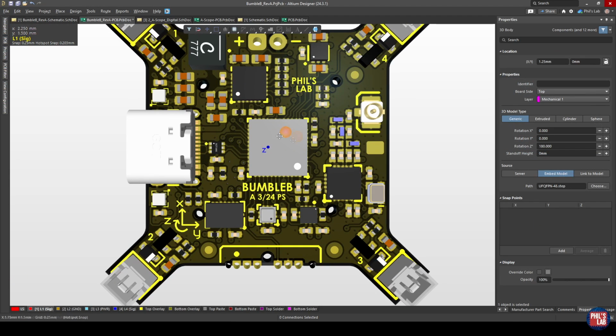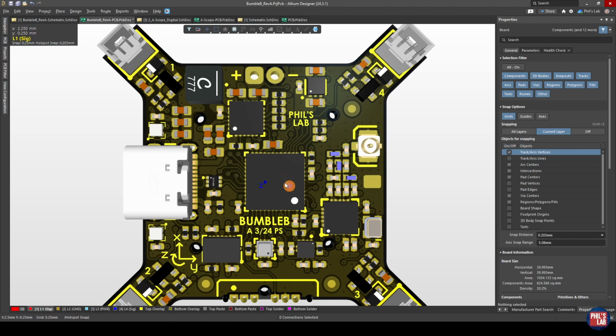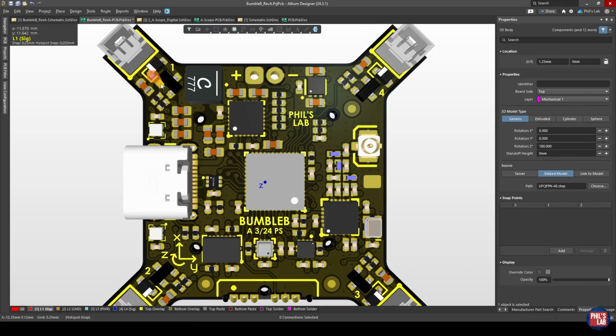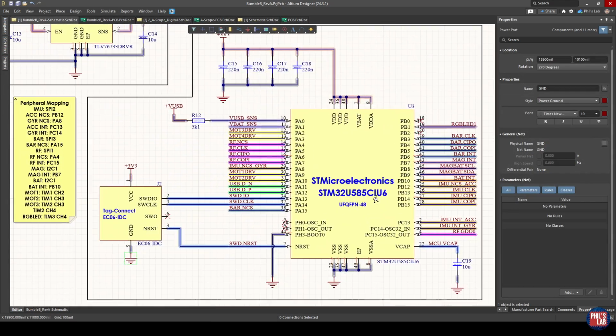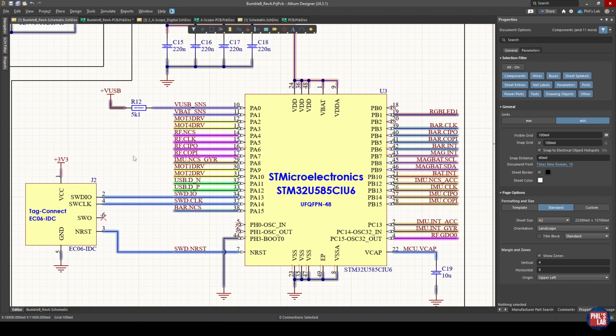Again, we have a microcontroller in the center connected up with various peripherals that most of the time, in 3 cases, use SPI to interface back to the controller. In terms of the schematic, looking at the microcontroller section, you can see I'm actually using separate SPI buses and interfaces between the various peripherals. This is again because I want to be able to use DMA and do parallel data transfers, for example, from the barometer, the accelerometer gyroscope, and the RF transceiver, so that I don't have to wait for one to complete to be able to talk to the next one, so to speak.